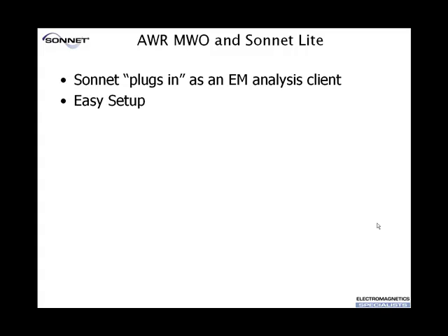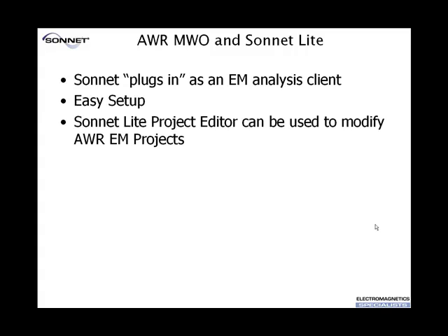The setup's very easy. When you install Sonnet Lite, it detects automatically the presence of the AWR Microwave Office environment and registers itself properly with the software. You'll see in the menus that the software is automatically made available, and we'll show you that in a few minutes. Now, you can also use the Sonnet Lite project editor for modifying the layouts in your AWR EM projects, or modifying metal types or other material properties as well. All of that information is available and can be changed if you prefer to work on your geometry or your materials in the Sonnet layout environment.